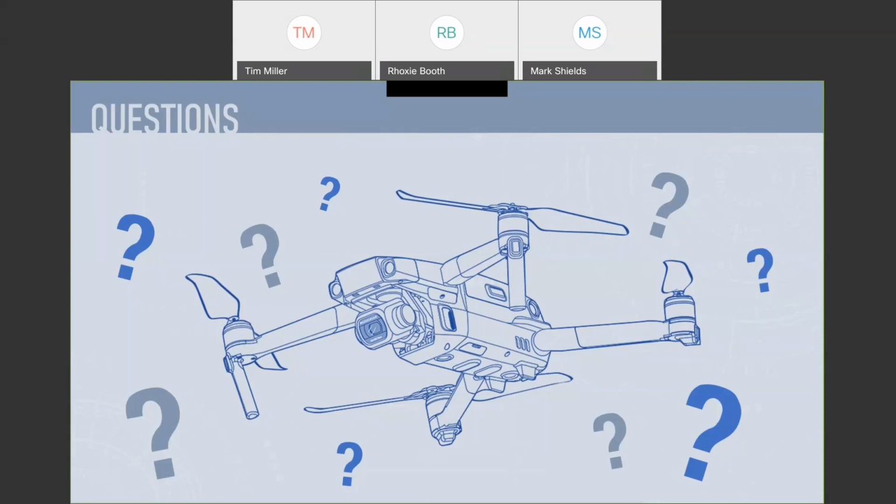Okay. And then can data be collected for 7 days straight on roadways? Also, is there a camera that can handle both day and night without having to be swapped out? Wow, that's a good one. For a survey like that, you would typically want to use something like a DJI Matrice, where you can set up multiple cameras on the unit itself. And if you've got it tethered, yeah, you could absolutely keep it in the air for 7 days. Okay. What is the max altitude with a tether? I haven't seen any tethers that are over 300 feet. I think that's the max altitude they've got right now.